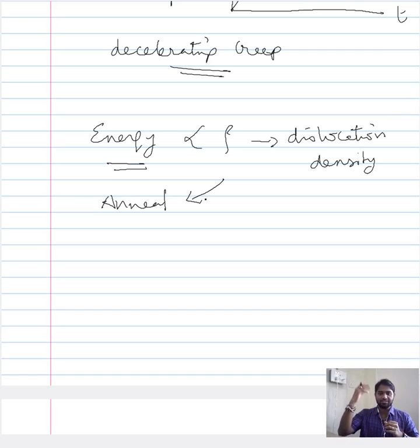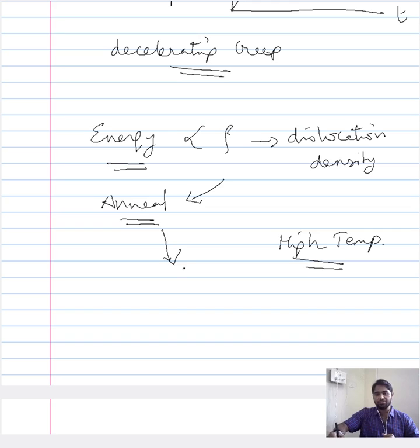Now, increasing the temperature of the material is nothing but what we consider in the creep testing. So, in creep testing, similar to annealing, we are not talking about an ambient temperature or the room temperature. We are talking about a relatively high temperature. So, ultimately what you are doing is you are introducing a condition that is similar to annealing during the creep testing itself. Therefore, whatever dislocation has been introduced by the load can also be annealed during the creep testing because of this increase in temperature.